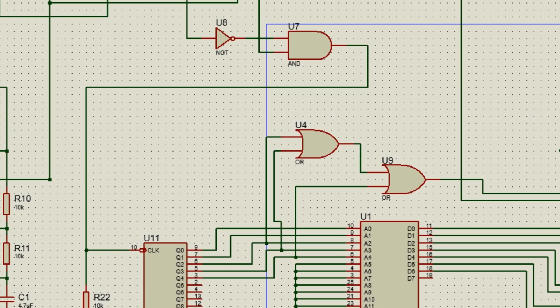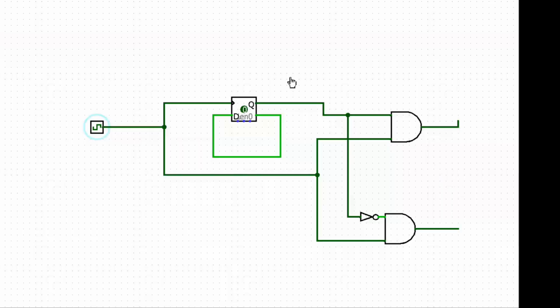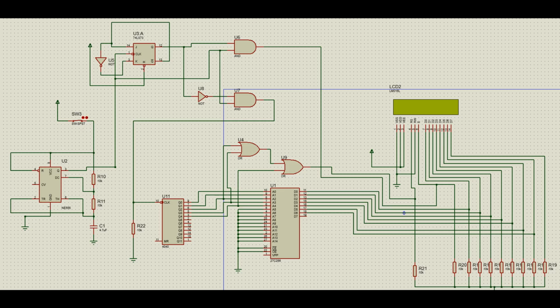We also have the control unit, and I need to explain how it works to send the clock signal at the right time, first to the memory, and then to the display. I came up with this simple solution. We'll need a flip-flop and some logic gates. See how it alternates the clock to each other. This is necessary because first, our circuit will select the data from memory using the counter, and after that, it will send the selected data to the display using another clock signal.